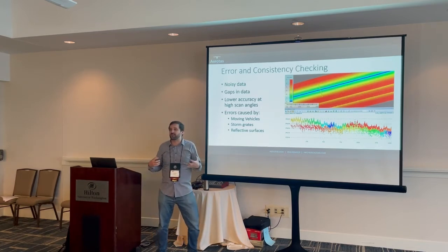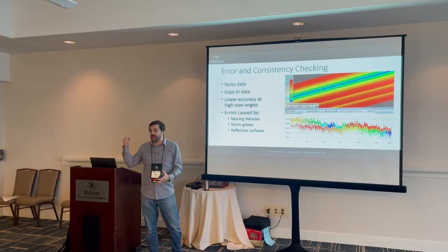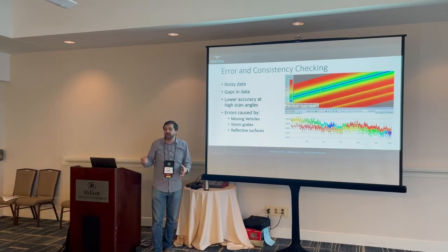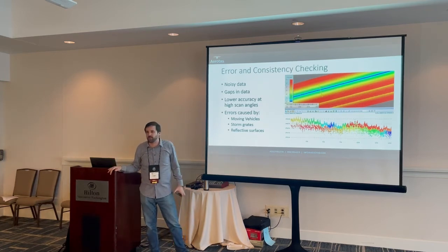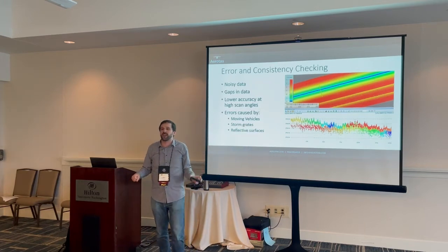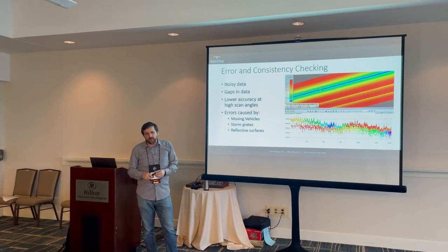Are there flight patterns and flight parameters, aside from just slightly higher overlap, that we can use to get much more reliable data based on the flight operations side? I said with photogrammetry, flight operations is so big, that's where most errors come from. There's probably a flight ops solution to this that we just haven't figured out yet what the perfect one is. Do you think theoretically this one wouldn't necessarily need patch tests because it's an integrated system, so those offsets never change?